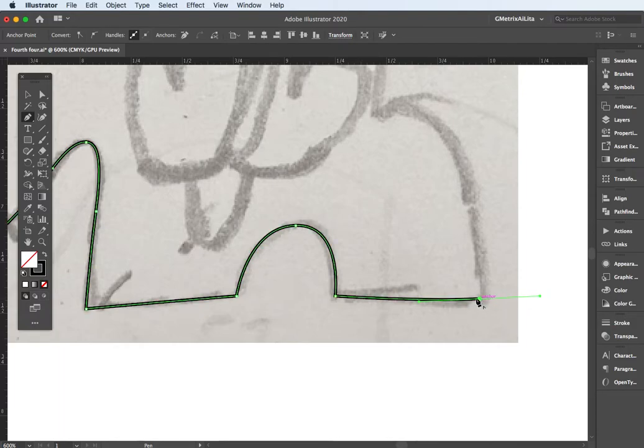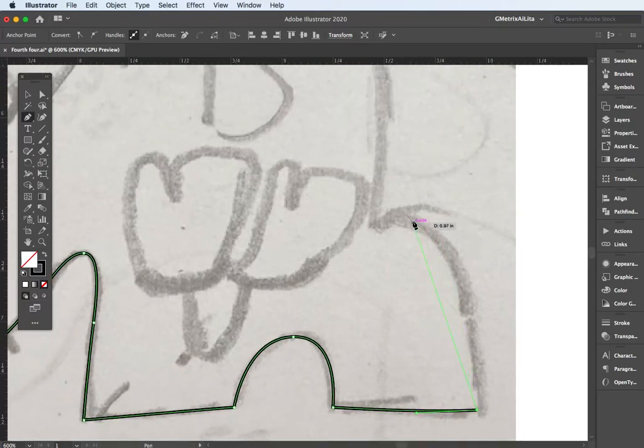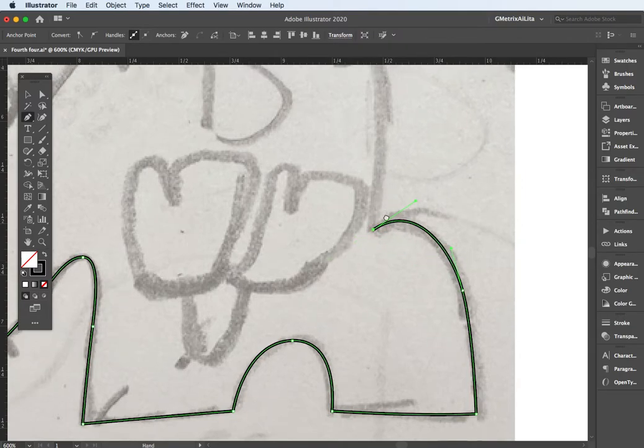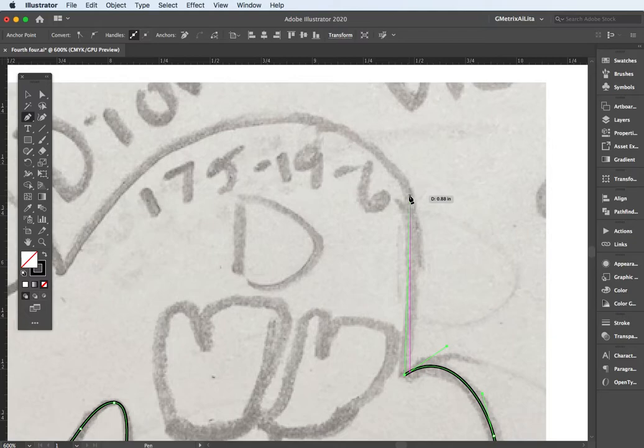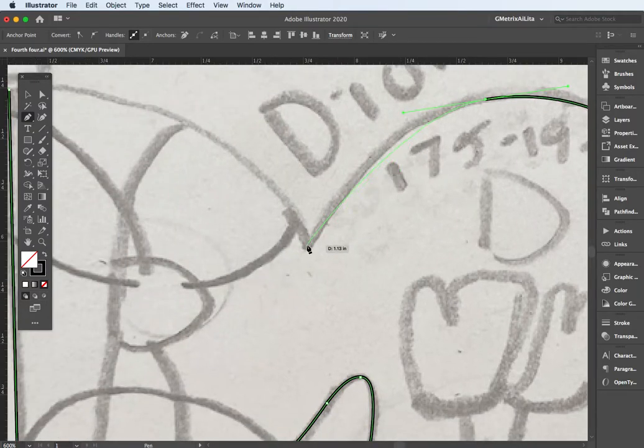And again, you can adjust all these different points, but there's the corner point to come up to this top piece here. You can see this one's a little too far, so I'm going to undo it and come up a little bit shallower onto this segment here. And that helps me make, you're trying to use the least amount of points to make these curves. And stretching it all the way across here. Like I said, this is kind of using that curve.